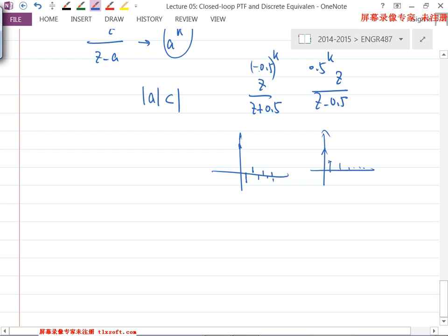So in other words, if you compare these two and think of a system response, it is positive, negative, positive, negative, positive, negative, right? Typically, you don't want that to happen, isn't it? Because if you're controlling a motor, you're giving the motor one command that is positive, the next is negative, and you have a very fast rate of change. That's very confusing. It's very damaging to the motor.